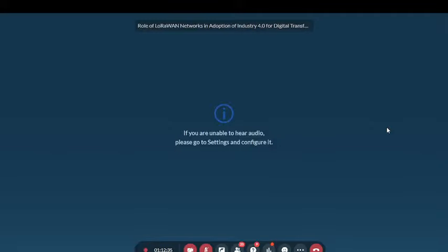But yes, if you want to manage more than one meter. For one meter, LoRaWAN is not the right solution if you don't have a public network. But if you have multiple meters, then you can deploy an RS-485 to LoRaWAN converter and send data from your home energy meter to the LoRaWAN network. We also have a DLMS to LoRaWAN converter that is used for the standard utility meters installed in our households. If you are not convinced with the explanation and have more questions, you can ask again.